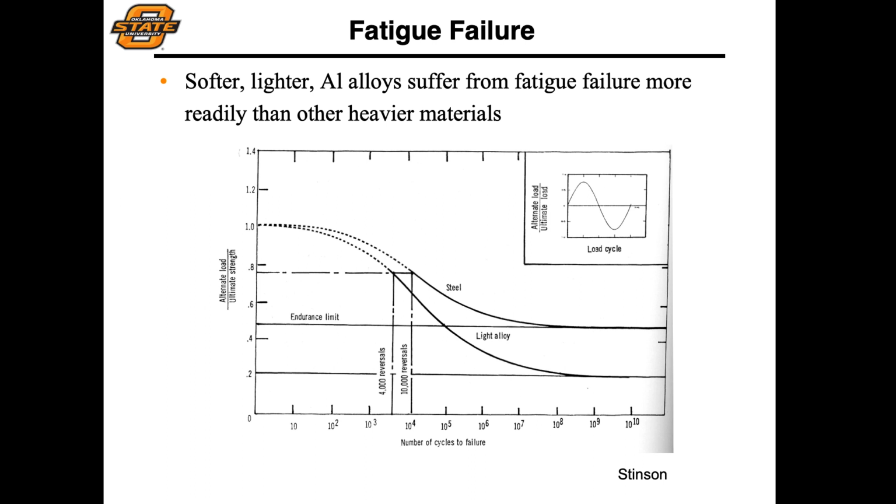Now, what we often see in aircraft failures is the impact of fatigue. Rather than a failure being immediate, what we're going to see is that material start to degrade over time as it goes through cyclic loading. Think about this in the context of your wing as it becomes loaded and then unloaded, loaded and then unloaded. For every flight, it goes through this process of being loaded to extremely high loads and then unloaded again, repeatedly, perhaps multiple times per day. So you might have this process happen 1,000 times or more a year, and you obviously end up with a lot of cyclic fatigue possibilities.